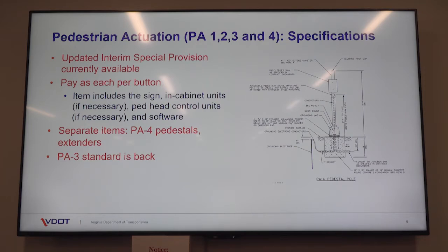Okay, was this considered with a conflict or not with another standard, that minimum lateral space between any fixed object is 1 foot from edge of sidewalk? Oh, sorry, say that again? We have a standard for minimum lateral clearance. Any fixed object is 1 foot from the edge of sidewalk.